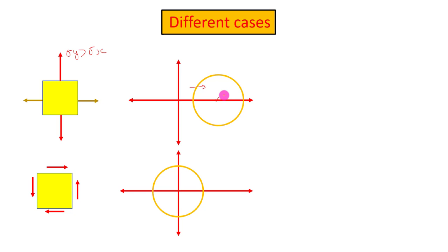For the pure shear case, if you look at this face, this is something important. What do you get? You will get a point corresponding to minus tau, and sigma will be 0. So 0 comma minus tau. This point will be somewhere here. Similarly, for the orthogonal face, you will get 0 comma tau. So that point will be here. Now if we connect these points and find the midpoint of this line, you will get the origin.